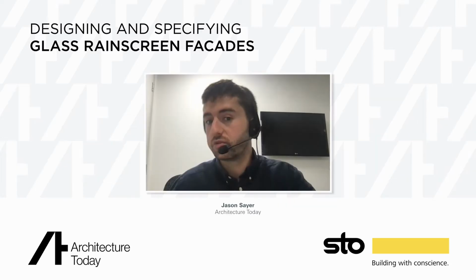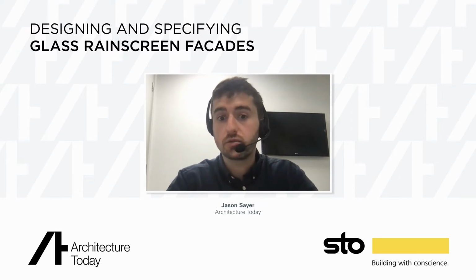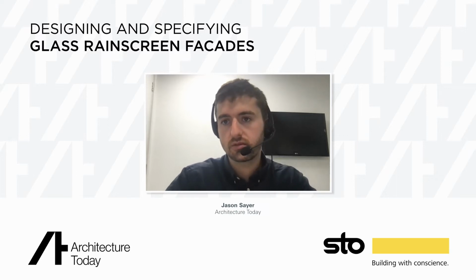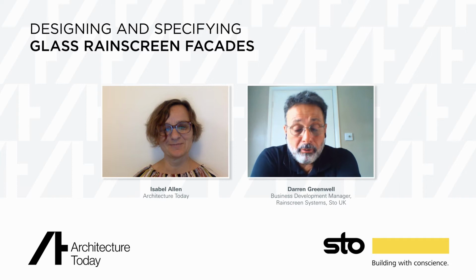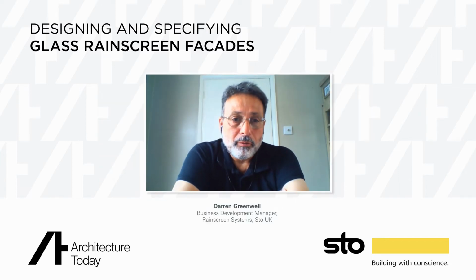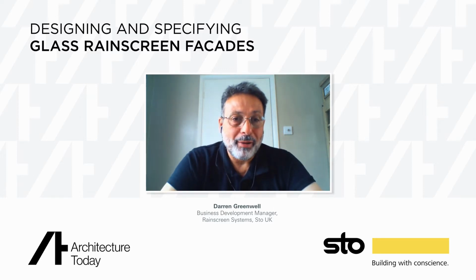Sure. I've actually got a question in which will go back to what you talked about with screen printing, and it's also related to the aesthetics. How can you incorporate signage in the glass panels? There are different ways that you can incorporate signage. The first is obviously to have the signage actually back printed onto the glass, either digitally or screen printing, and then it's baked on.